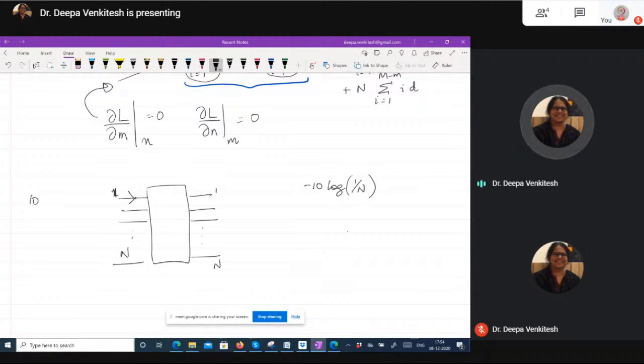So essentially, insertion loss is what is given. If I give input at port 1, between port 1 and port 1, I measure the loss is 9.33 dB. In port 2, I measure 7.93 dB, which means port 1 is more lossy. It has more excess loss than port 2, obviously. Port 3 is 7.53 dB, slightly even better. Like that, you go all the way up to n equal to 7, which is 9.04 dB.